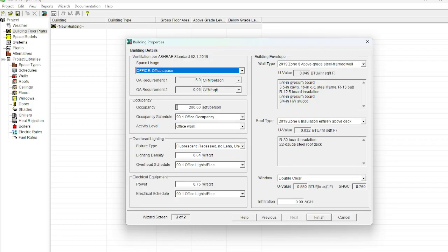All right, occupancy, 200 square feet per person. Okay, well, notice the min there is 0.1 square foot per person. So literally, architects know that if you're at a desk, you actually get 3 square feet per person. And that's how many people you could cram into these spaces. Reality is, we're never going to cram one person into 3 square feet. That would be a foot and a half by foot and a half, which is basically just standing next shoulder to shoulder with somebody. So we're going to give this a little better number. Let's put it down as 20 square feet.